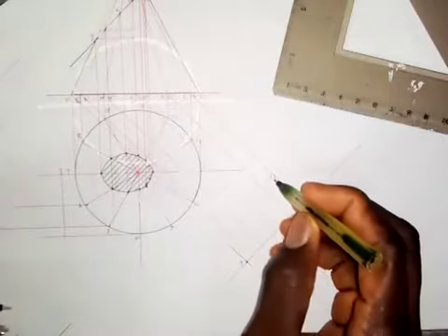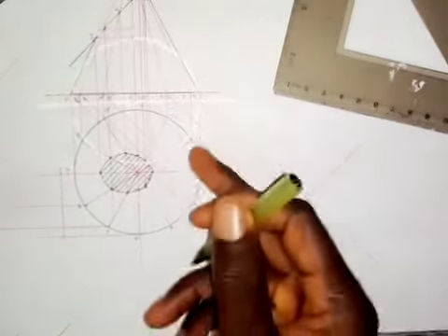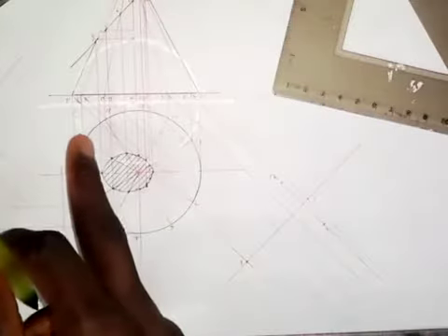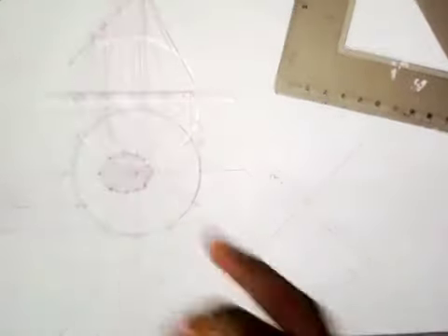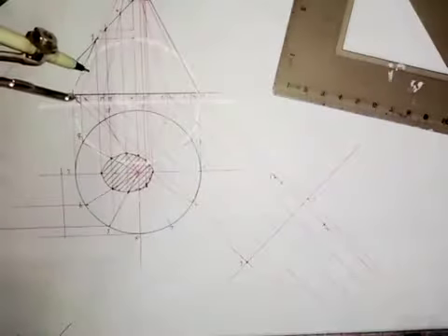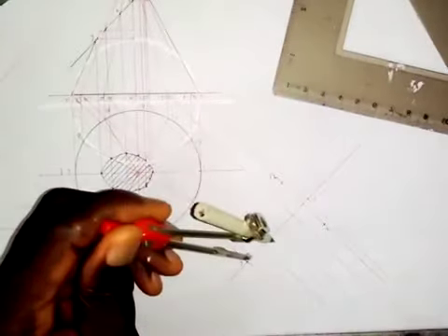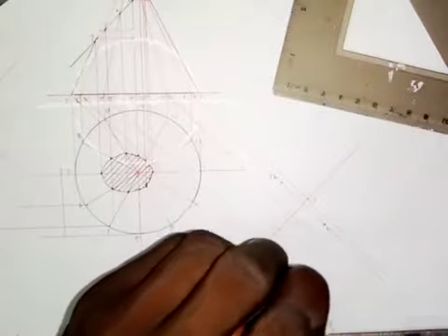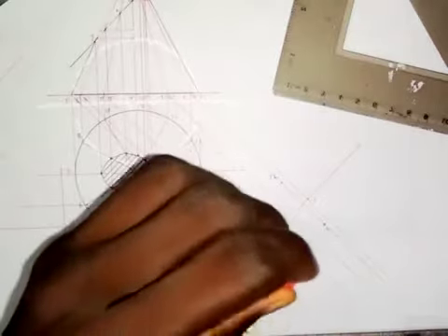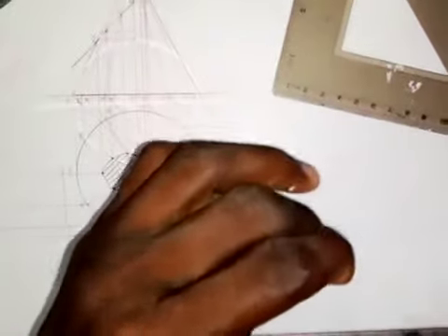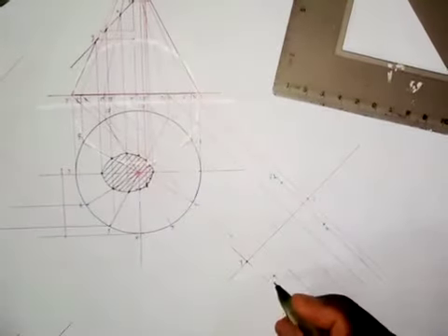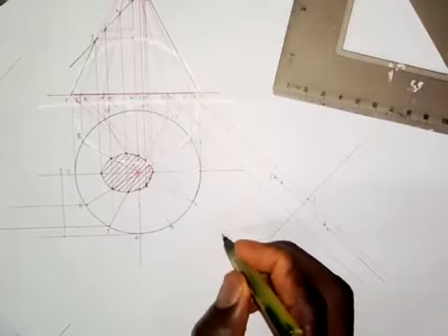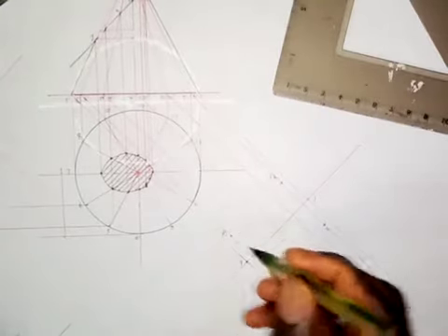Then here on the circumference of the circle, we also have 6 and 8. They occupy the same position as we have for 2 and 12. So just come here and follow 6 and 8 here. Put the point of the compass here, make an arc here, make an arc here, and then make an arc here on this side. This point here is 6, and this is 8 here. So it's very simple as I'm doing it here.